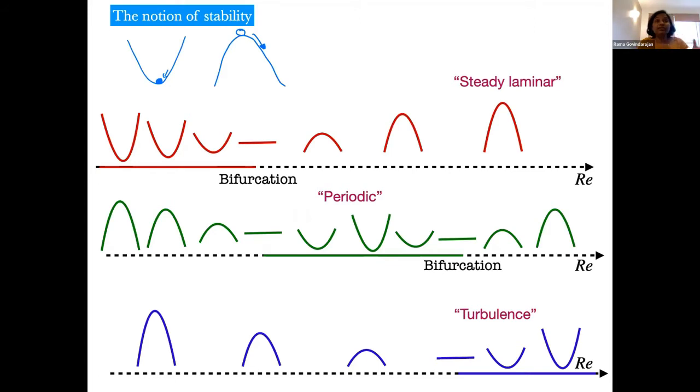From the previous two examples, we've seen that our notion of stability is just what a child will learn in school about stability. It's exactly that notion. Like, if you take a valley and you've got a ball here, you perturb the ball, it will come back to where it was. And this is stable, whereas a ball on top of a hill is unstable. So, a valley is stable and a hill is unstable. And in flow, we have the same concept, but we can't think in terms of valleys and hills because it's not always potential flow.